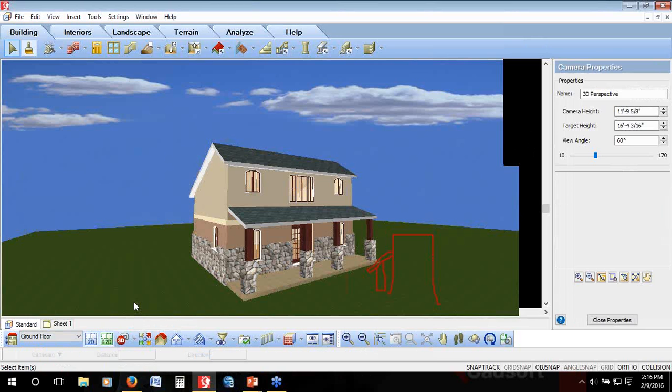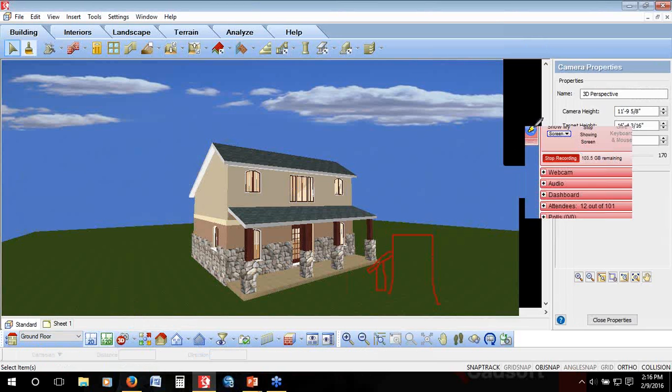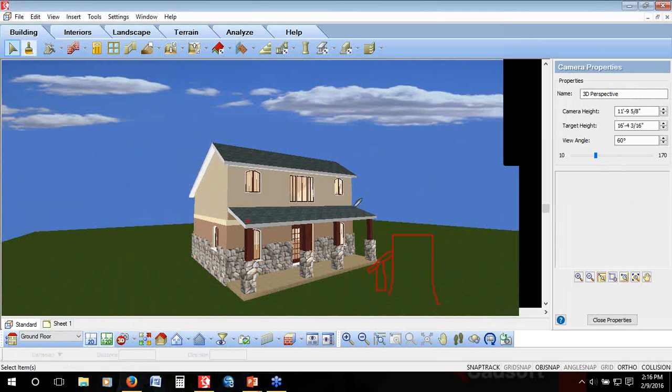So I picked the 4 corners to, first of all, form the roof by picking points. I picked out here, I picked this corner, and this corner, and it originally created the hip style roof. And then by showing it the sides that I want to be a gable, sides where I wouldn't normally hang a gutter or an eaves trough, it automatically raised the roof in those sections so that I have my slope.